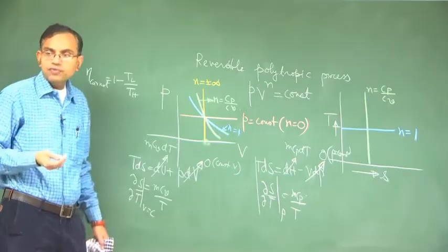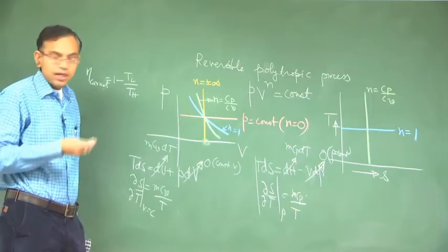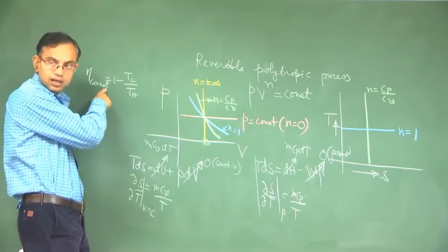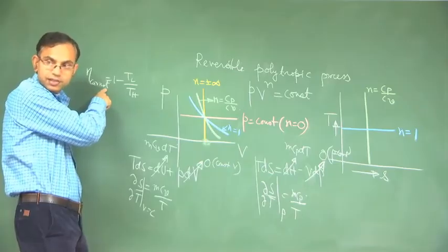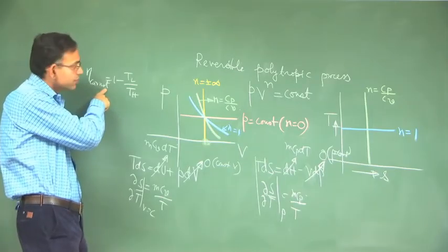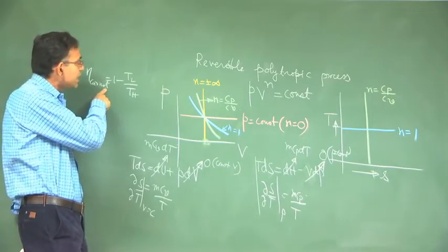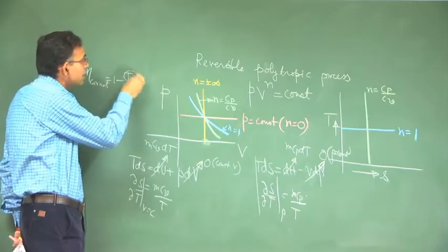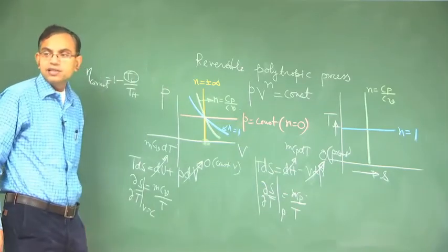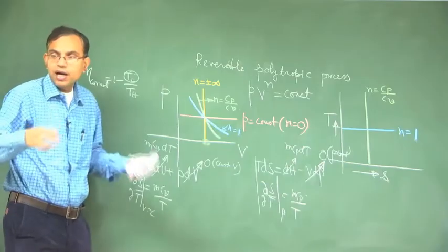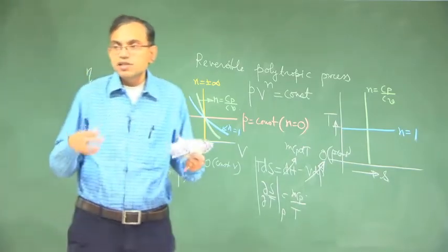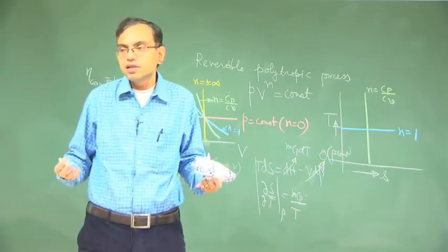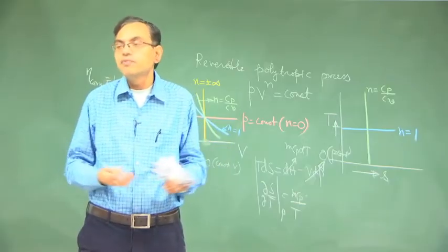Now by second law of thermodynamics, the efficiency of Carnot cycle should be less than 100%, Kelvin Planck statement. So if that will be less than 100%, TL cannot be less than 0. So that is why the concept of absolute temperature comes, it cannot have a negative value.